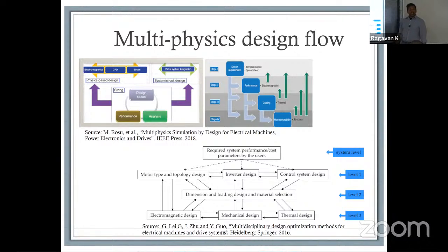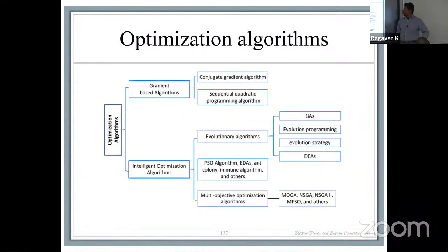I'm not saying that is necessarily what is needed, but this has been one of the multidisciplinary design optimization methods, where you're looking at every one of them simultaneously. This was a more linear method, which you can talk about in classic design. You're going from stage 1, which is template-based spreadsheets, stage 2 is electromagnetics, and then thermal, and then structural. And then it's iterative. If this doesn't work, go back. This doesn't work, go back. Doesn't work, go back. So you basically figure out what your entry point or recalculation point for your system is going to be. So you have multiple ways of tackling the same problem, and depending on the resources available, you might pick one of them.